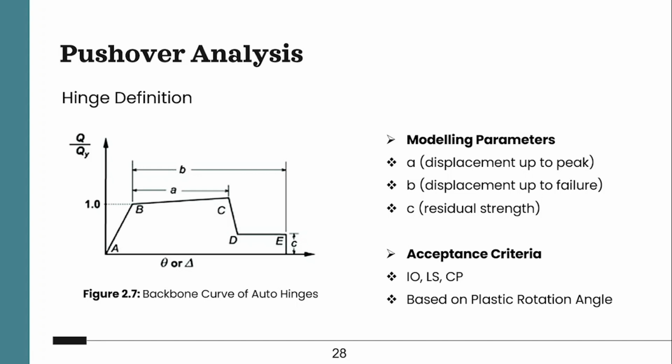What we mean by hinge is that when a real life earthquake occurs, like a very strong earthquake, the structure will not remain elastic. But as concrete is very brittle, to make it ductile, what we do is provide closely spaced stirrups at the end regions. Mostly the joint of the pier and the pile cap will have a lot of movement, and that's why we provide hinges at that location and also at the pier top.